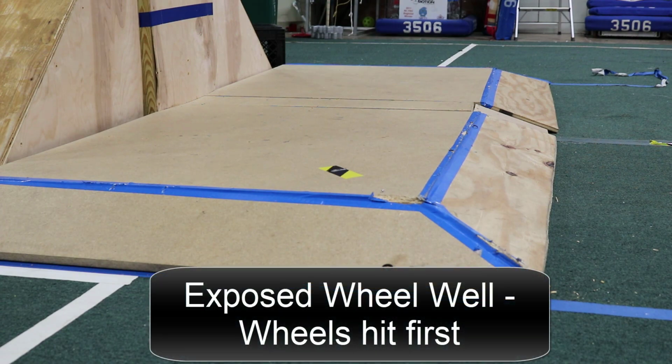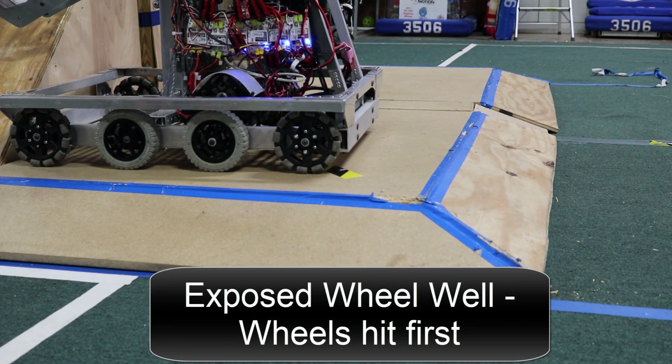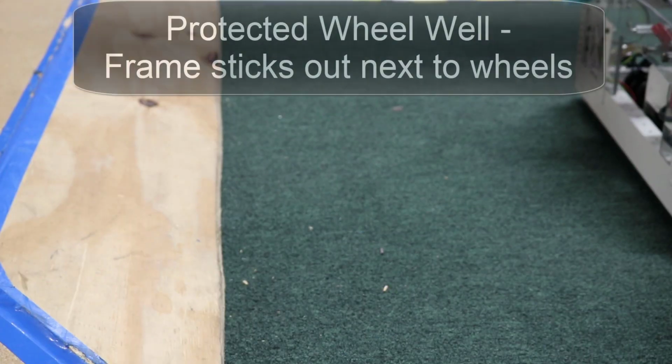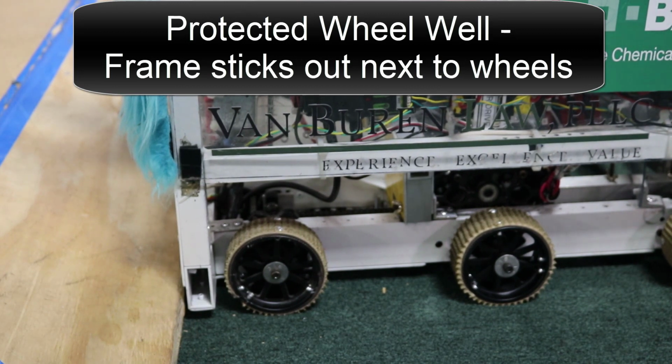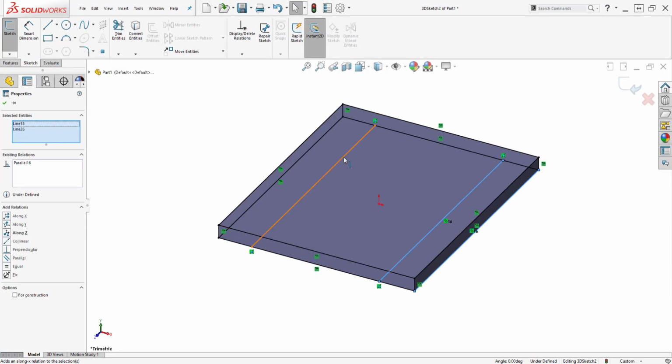When you have an exposed wheel well, your wheel is going to strike an object before your frame, and this allows you to have a much lower frame and smaller wheels when you need to go over some large obstacles. A protected wheel well is easier to mount bumpers to, so your trade-off there is pretty simple.